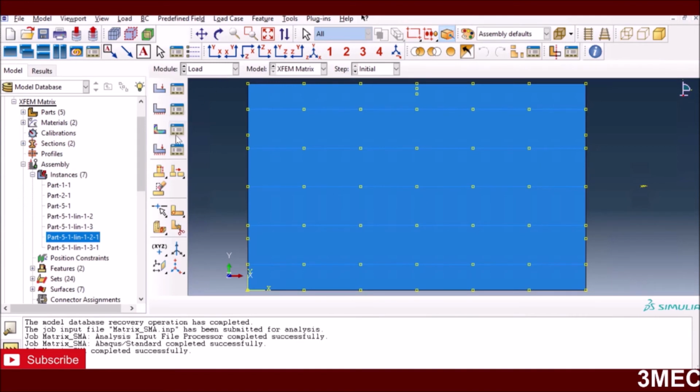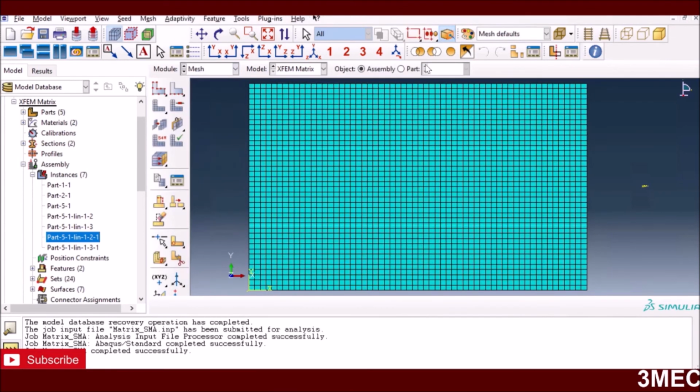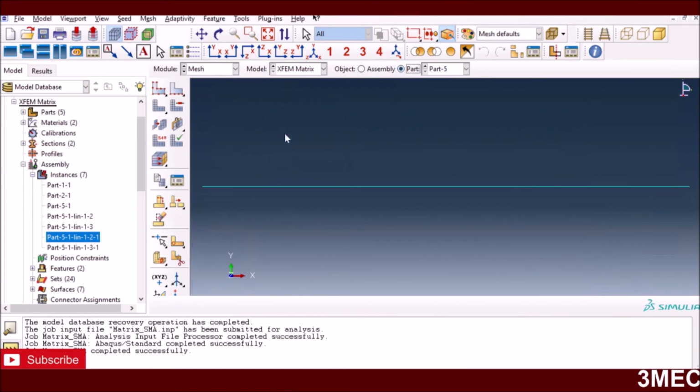But I think if you assume that it's a very small sample and diffusion takes place really fast and everything is uniformly heated immediately, then you can just apply this predefined temperature condition here directly, and I think that should be enough. But again, I leave it for you guys to decide. Mesh is the same. You see, this was a mesh for the fiber, and I use one element size for the fiber, sorry, and that was for the matrix.